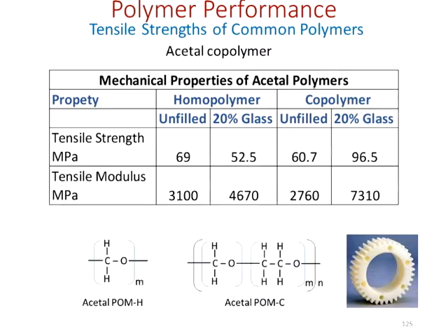and then we take those same systems and we fill them. We fill those with 20% glass, and it's pretty interesting to note what happens when the homopolymer is filled with 20% glass. Its tensile strength is less than that of the copolymer. So you see, that's pretty interesting.